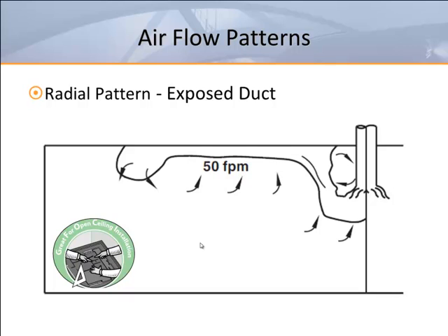Diffusers that have a built-in negative pressure pocket are identified in the Titus catalog with the insignia shown here. This means that these selected outlets, when used in an open ceiling layout, will still discharge air in a horizontal air pattern. Without a ceiling, the jet will entrain air on both sides. Thus, the throw to 50 feet per minute will be shortened by 30% from the catalog values.